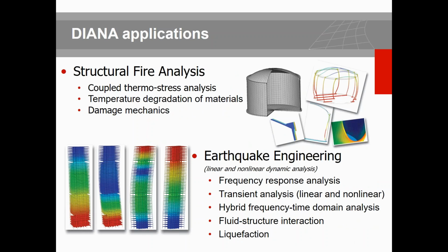For fire analysis, based on the model code or based on the user-defined input, you can perform a fully coupled thermostress analysis and identify the effect of, for instance, fire in a tunnel or fire in a building for 2-3 hours, and how this could cause a progressive failure in the structure. So some of the key and important infrastructures need to be checked versus some sort of reference curves from the RWS or other known references, and check the overall stability of the structure in case of fire.